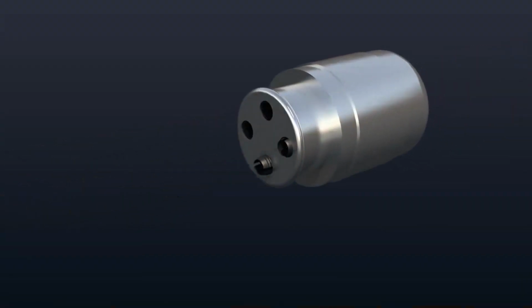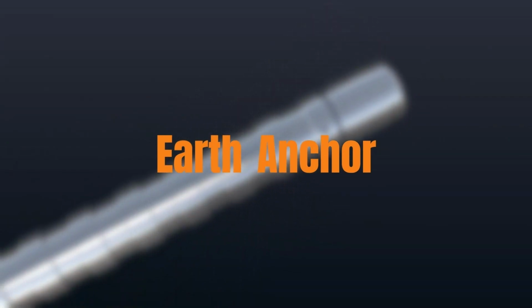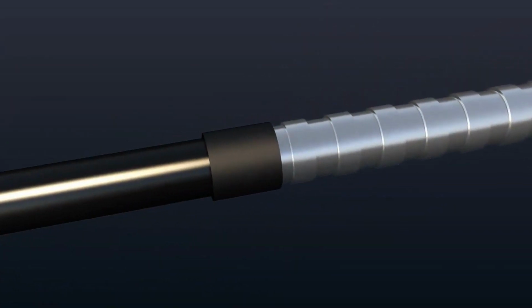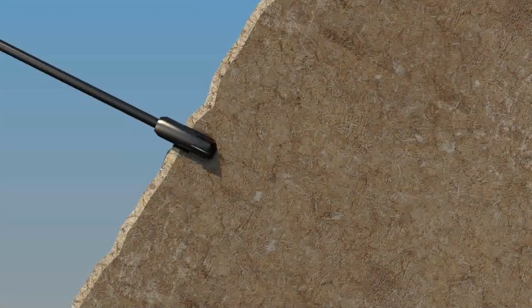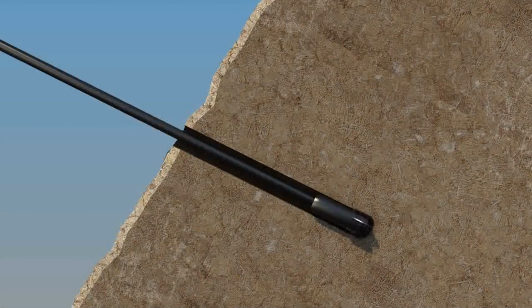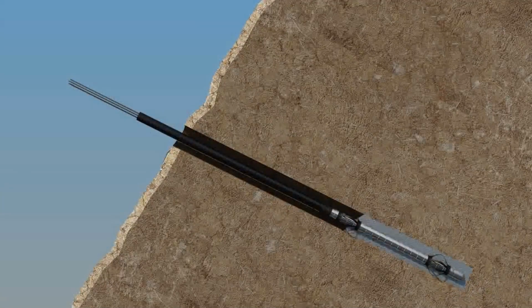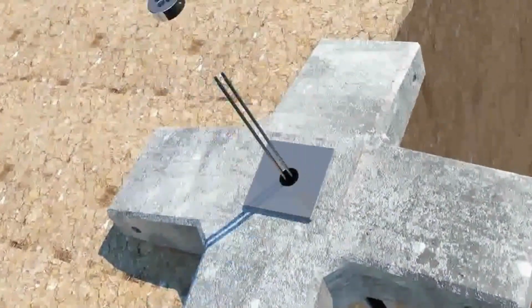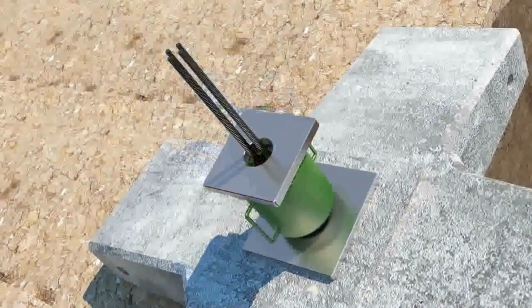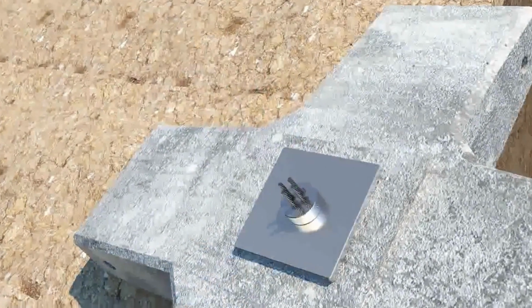The way to support this earth retaining wall is the earth anchor. The earth anchor method, which is generally used, is a method of drilling into an earth retaining wall instead of a brace, inserting tensile materials such as steel wires into it, grouting with mortar around it, hardening it, and then applying tensile force from the outside. Earth anchor is also called a removal anchor because it is usually removed when it has done its job.